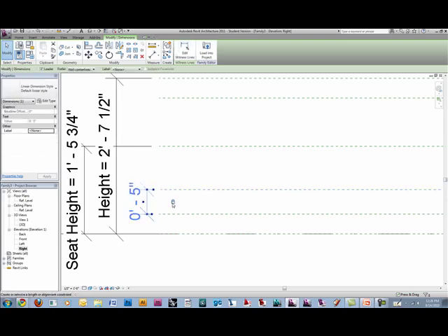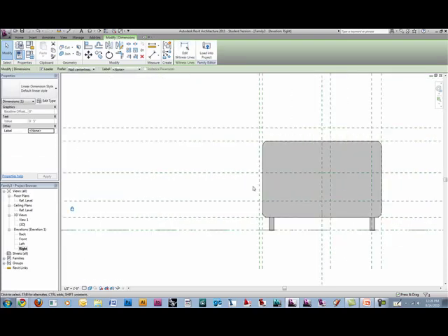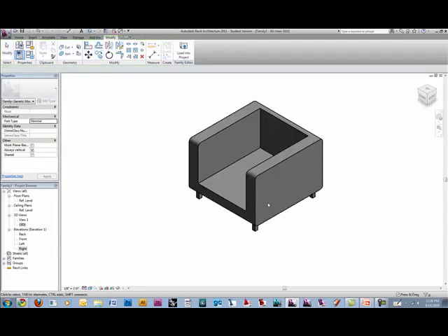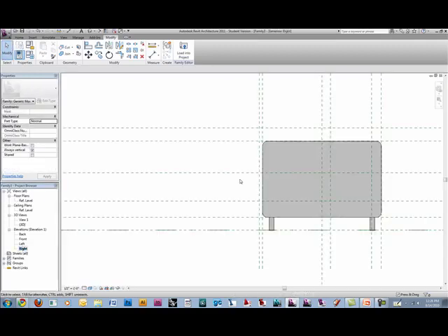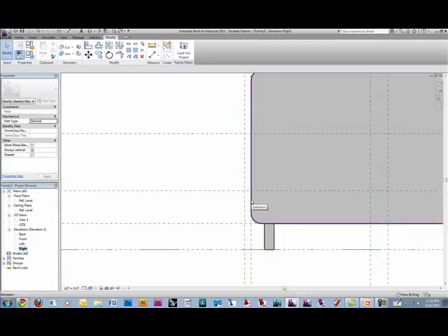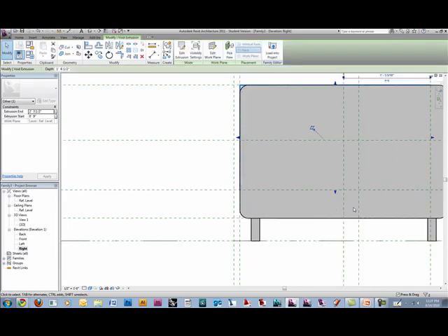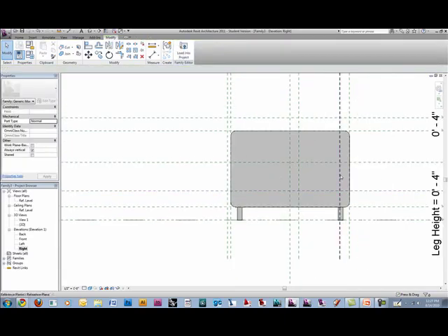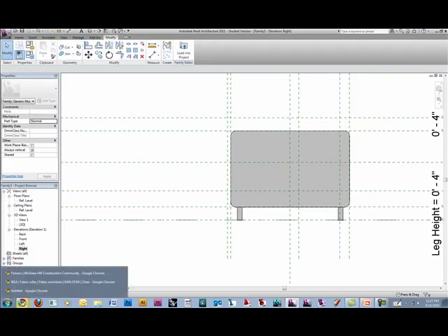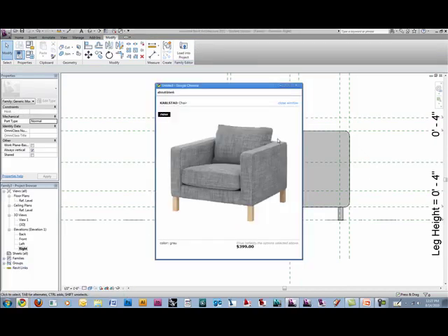So now I'm going to lock it. And it should have moved the geometry with it because I made it all parametric. It should have. Let's check. Yeah, it looks that way. See there? Boop. Changed the reference plane afterwards and it was all good. Alright, so now we have the cushions left. That's pretty much it and we're done. We can add the material parameters and call it quits.